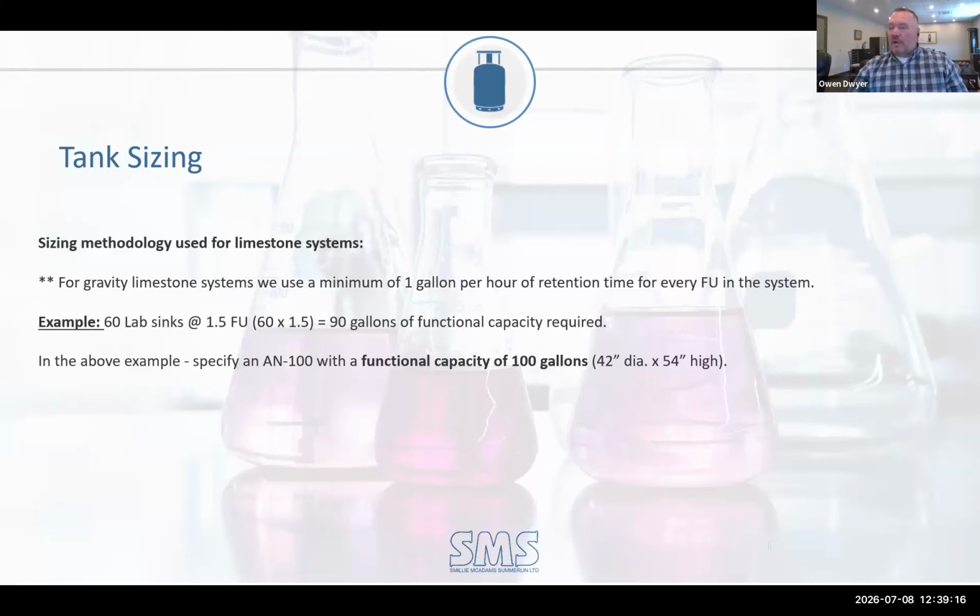So pi r squared h is the volume of the cylinder. We're going to talk about that, but I can't stress enough how important it is in your spec to specify as much detail as possible with respect to neutralization tanks. So unlike the piping side, you're going to tick the boxes based on chemical, temperature, plenums, sprinklered buildings, vertical shafts, etc. When it comes to neutralization, when you size it, you're sizing it, especially for limestone. I'll talk about injection systems shortly. But if you're coming up with a number, you look at a manufacturer's literature, you can't find a 90 gallon.